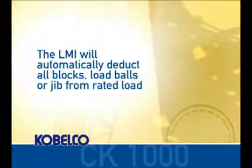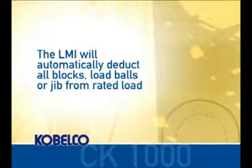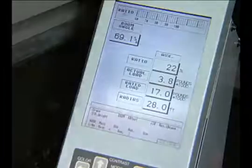The rated load is what the crane is able to pick at its present configuration. As an aid to the operator, the LMI will automatically deduct any unused block or jib from rated load. The radius is the distance from the center rotation of the crane out to the load block.